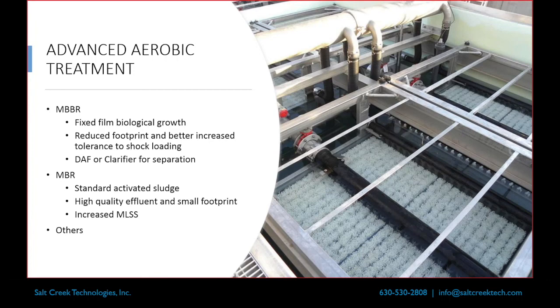So you're generating a really high quality effluent stream, really good if you're looking at reuse. And the other benefit is that you can increase the MLSS of your activated sludge system. So you're able to do a lot more aggressive treatment of that waste. So you can usually put a lot more BOD into that system, get a lot better treatment on a smaller footprint.